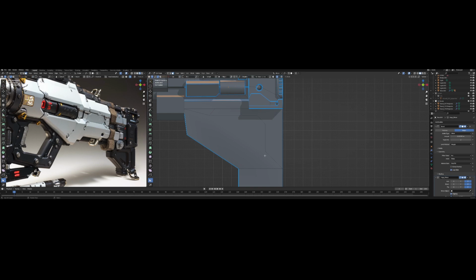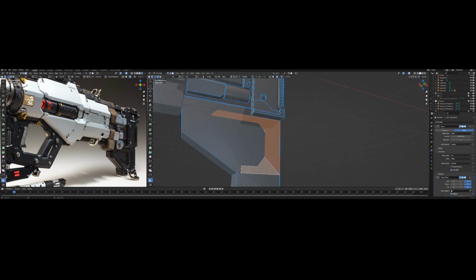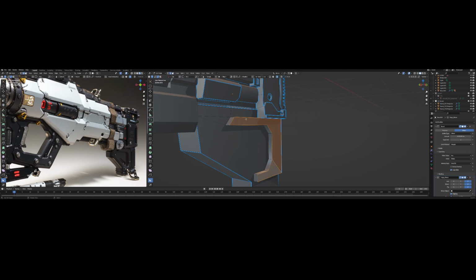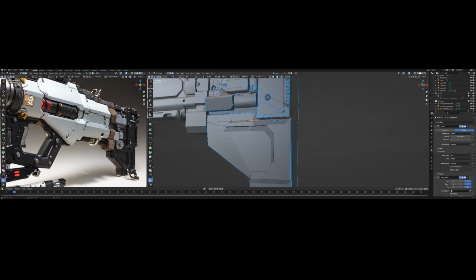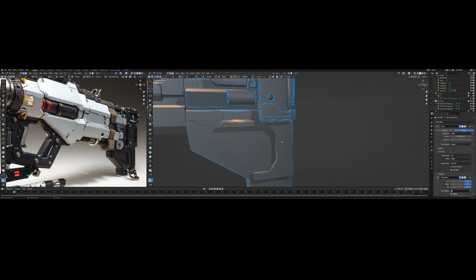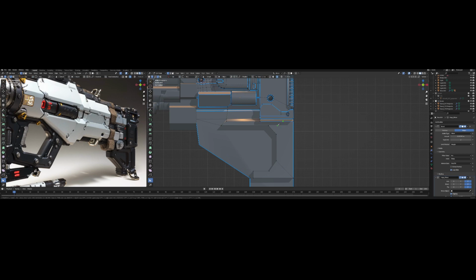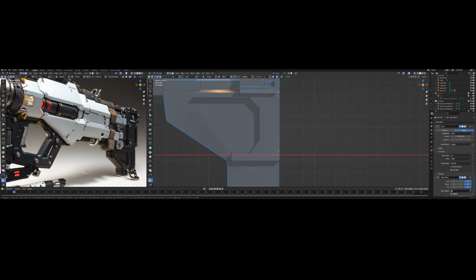But if you press Ctrl E, go to edge bevel weights, and remove the edge bevel weights, another color will be displayed. I think it should be the edge crease. Then you just press Shift E and press 0 to remove the edge crease.